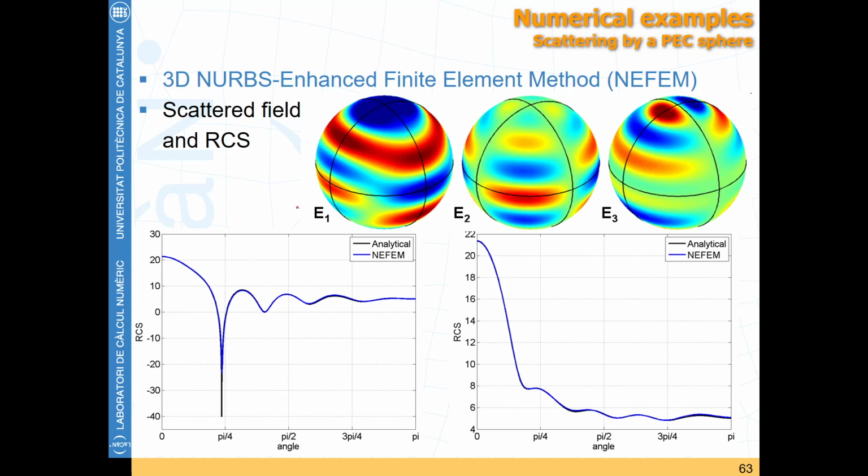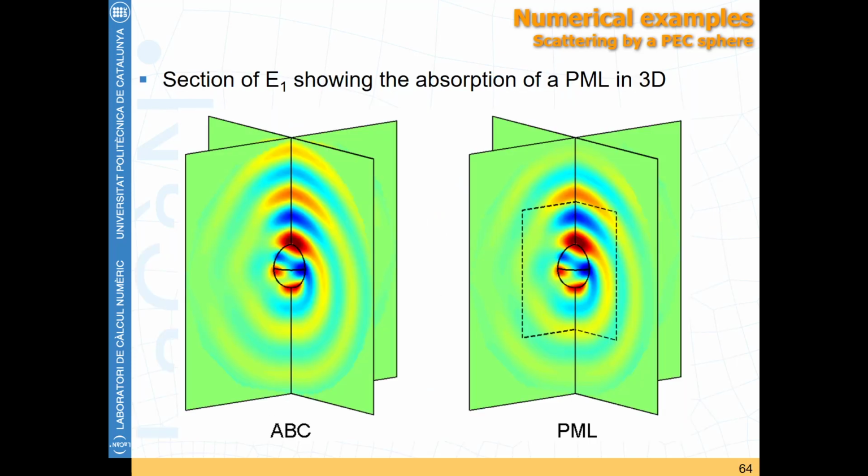And you can also extend that to the absorbing PML. You need to absorb at your boundaries and check that it is absorbed in this direction, and also in that direction, and that direction. You may need a given width of your PML, but it works, and that really decreases the effect of the boundary.